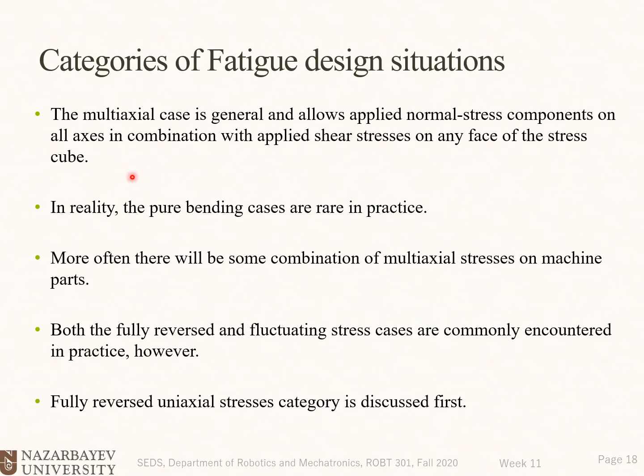The multi-axial case is general and allows applied normal stress components on all axes in combination with applied shear stress on any face of the stress cube. In reality, pure bending cases are rare in practice. More often, there will be some combination of multi-axial stresses on machine parts. Both the fully reversed and fluctuating stress cases are commonly encountered in practice. However, the fully reversed uniaxial stress category is discussed first.